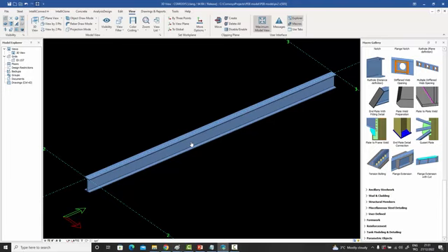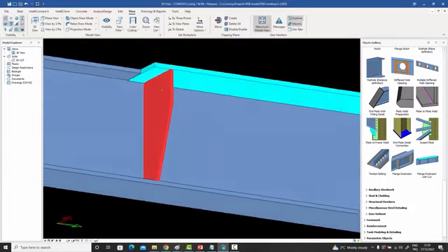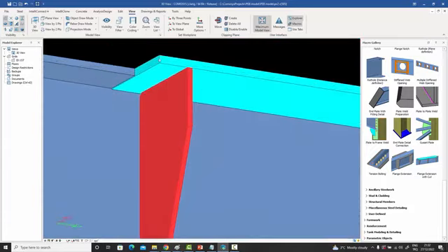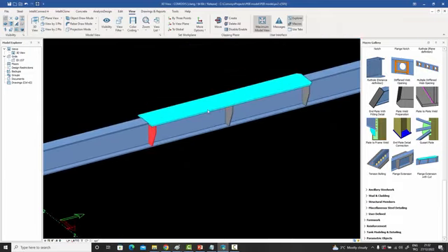All you do is you select the beam, and then you select a point on the beam, and you can do that very easily with the direct entry method, as you know. So you can say dy 2000, and that'll give you a point on the beam wherever you want, basically. And then you can put another one ahead of it, and when you do that, it'll create a flange extension at that point by cutting out the flange of the beam, and replacing it with a plate, one of the available thickness plates, and it will basically create this widened flange between those 2 points.